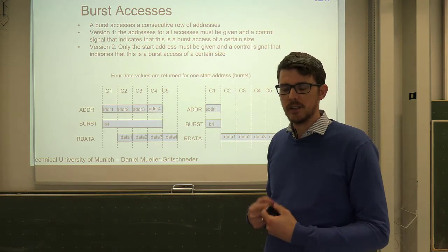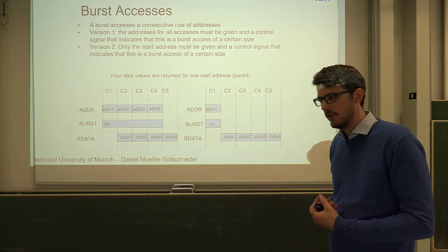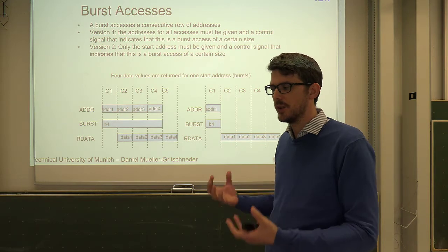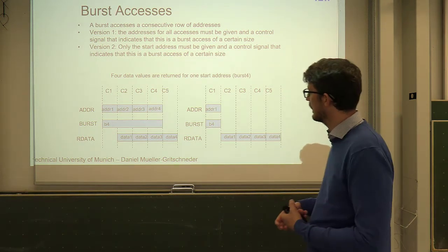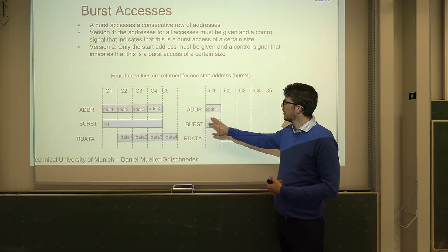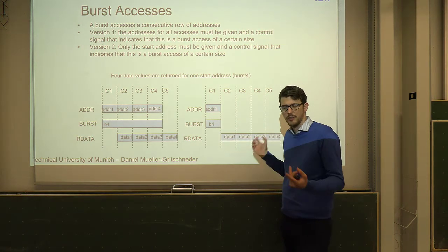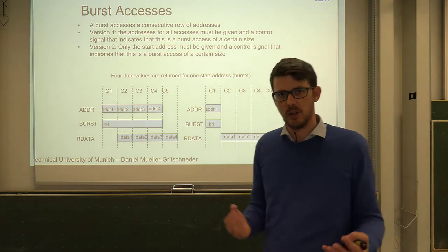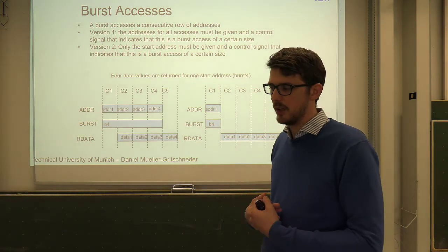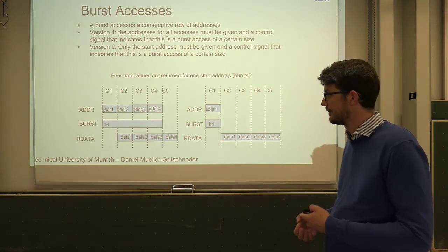But to get to your on-chip bus, for example, maybe in between there is a cache, right? And therefore, when you have a cache miss, then the cache has to load a new block of data. And then actually the cache will basically create this request and will say, okay, now I have to load this address because this was an access, but I'm also loading a complete cache line or block of data. So give me all other information on this cache line too. And therefore, these burst accesses are something you see a lot as soon as you have caches or direct memory access controllers and so on.